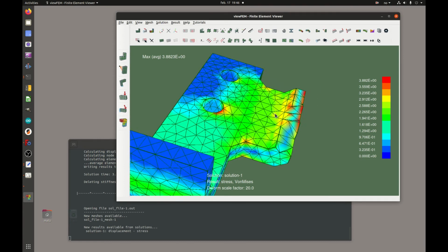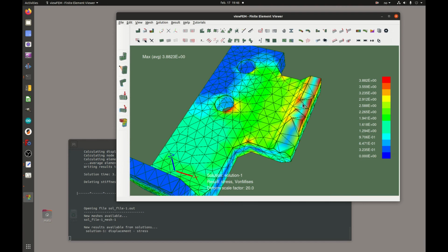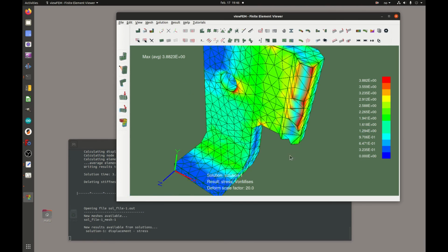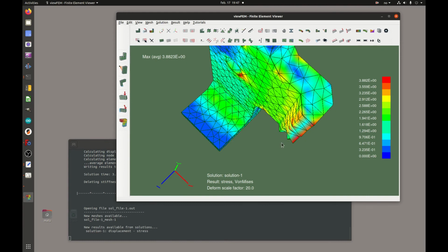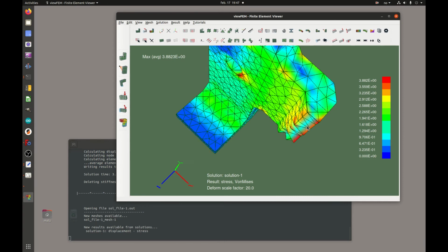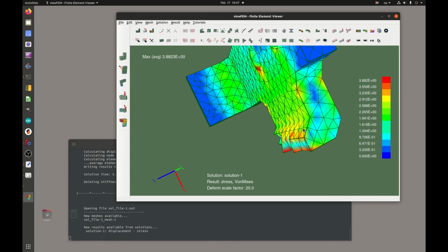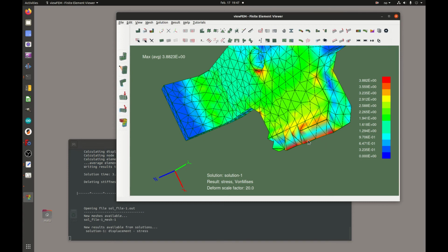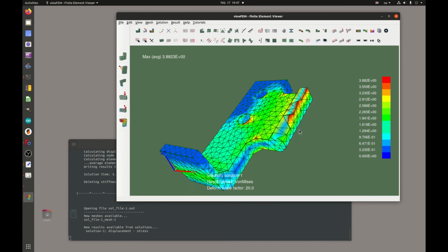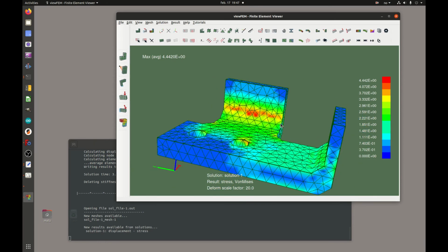So obviously here, I mean, these stresses are so small, it doesn't matter. But if this was an area of concern, then obviously this should probably be a finer mesh than this. And you can click show elements here to restore the stress plot.